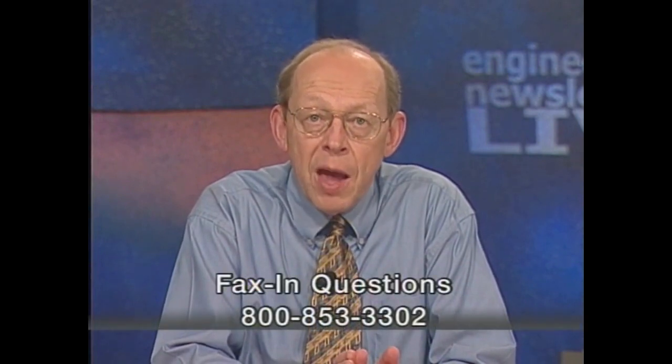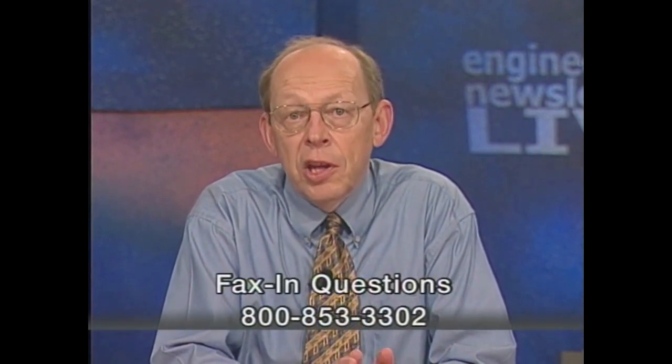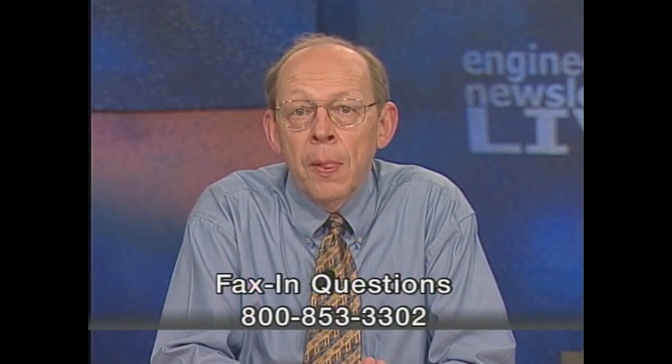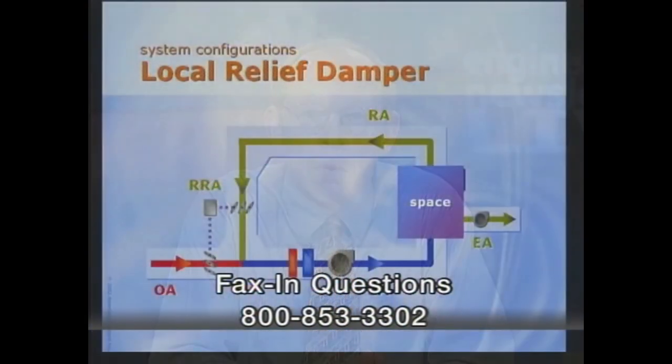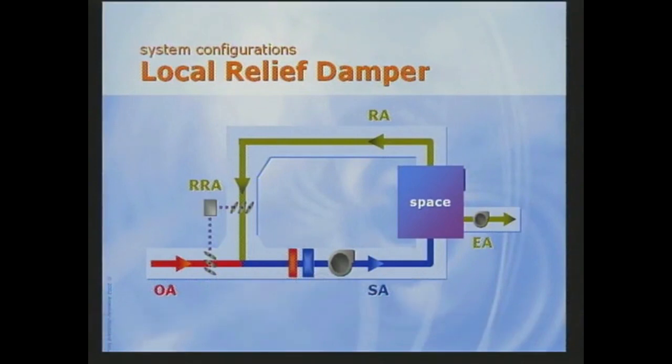For local relief, a non-motorized, gravity-operated relief damper, commonly called a barometric relief damper, is installed in or near the occupied space. Outdoor air is brought in by the air handler. A mixture of outdoor air and recirculated return air is supplied to the space. In some of the space, supply air is exhausted by local exhaust fans.